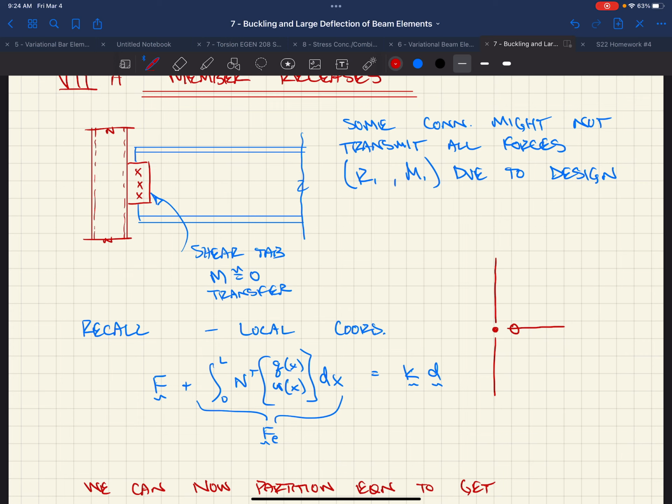So then you end up doing that to all of these connections, and so now it's really a linear elastic thing where if you start pushing on the beam and you start rotating it, the friction forces are really going to be transmitting some of those forces. And so they're trying to account for that by not making the shear tab too big, right? So that if there's one thing that is the softest element in the system, it's the tab and it can rotate. And so that it does overall behave like this pin member.